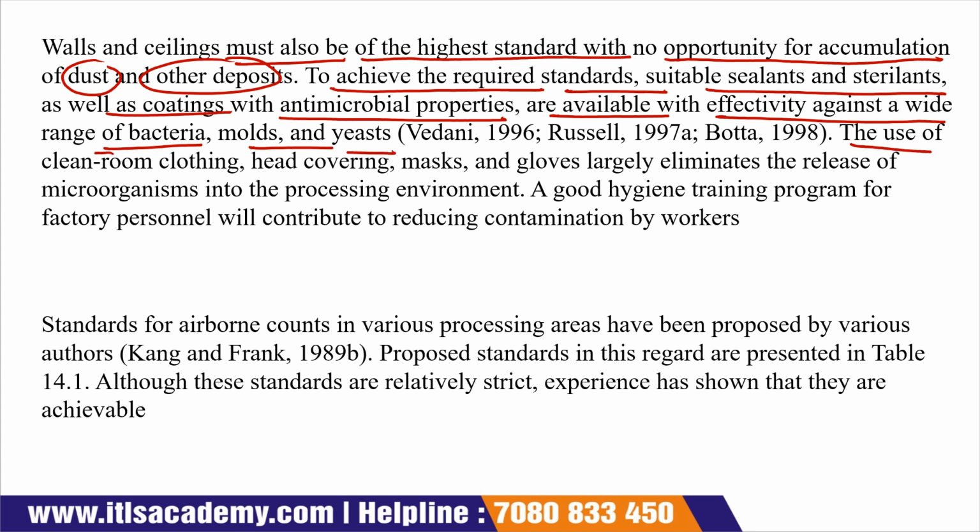The use of clean room clothing, head covering, masks and gloves largely eliminates the release of microorganisms into a processing environment. Okay, if clean room clothing is used, the head should be covered, masks and gloves should be worn, and ultimately they eliminate the release of microorganisms into the processing area.